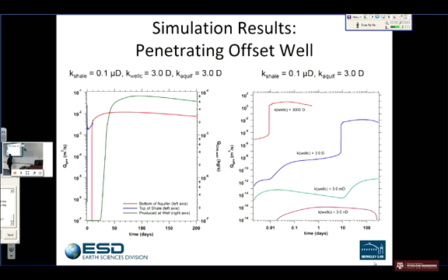But what you see happen is boom, this gas coming up. Well, this is the initial gas in the fracture and it just goes up all the way. By the way, if we assume that initially we have nothing but water in the fracture, we will never see any gas coming out. End of story. And what you see happening over here is what happens at the base of the aquifer for different permeabilities of this abandoned well system.